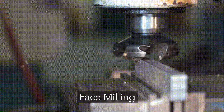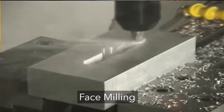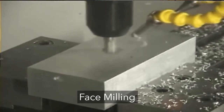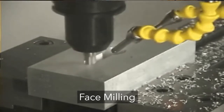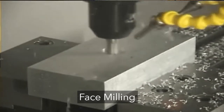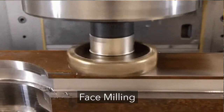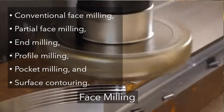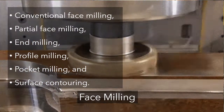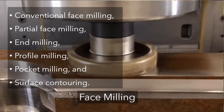In face milling, the axis of the cutter is perpendicular to the surface being milled, and machining is performed by the cutting edges on both ends and the outside periphery of the cutter, as in peripheral milling. Various forms of face milling exist. These include conventional face milling, partial face milling, end milling, profile milling, pocket milling, and surface contouring.